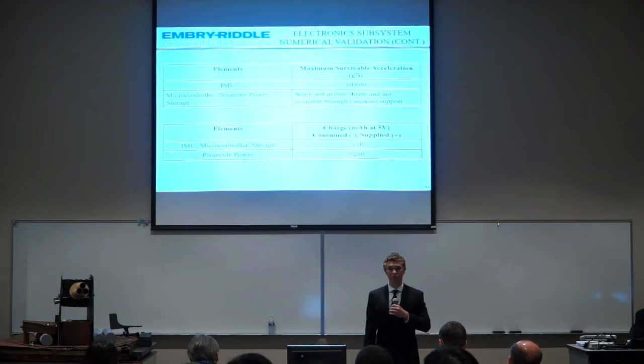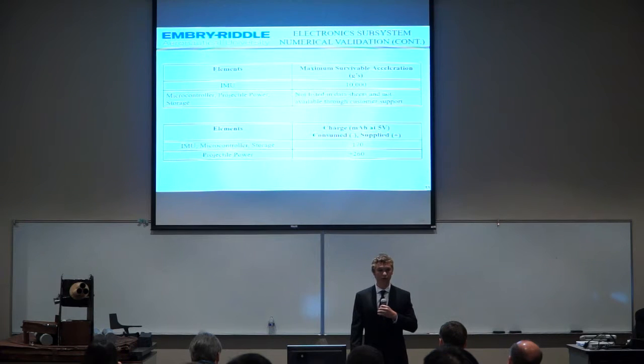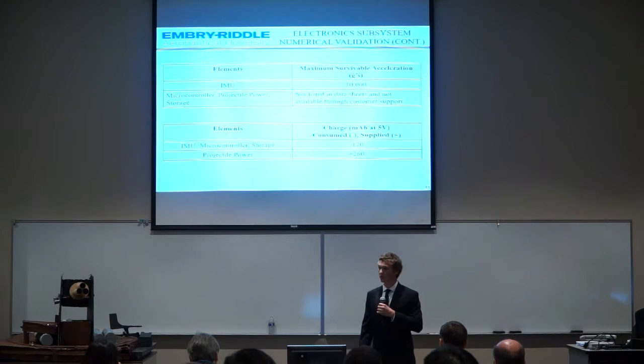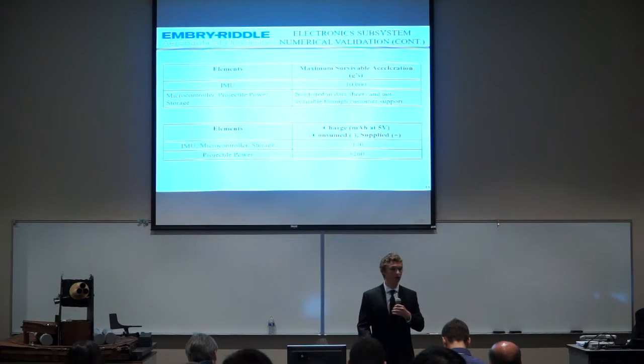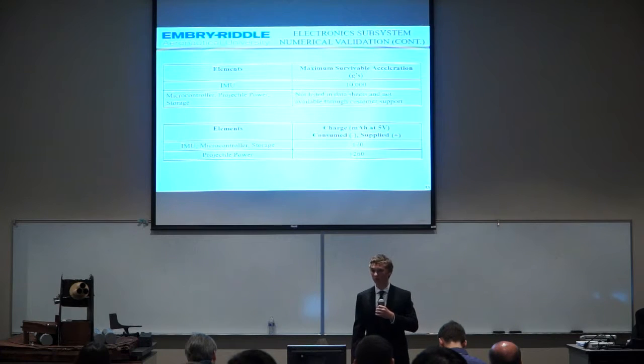The final design metric, which was the power produced versus power consumed, shows that the IMU, microcontroller, and storage elements all use 170 milliamp hours, and we are capable of having 260 milliamp hours from our projectile power. Therefore, we are able to power all those elements for 10 minutes.